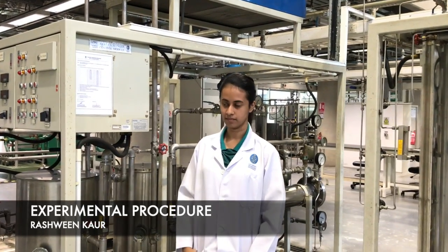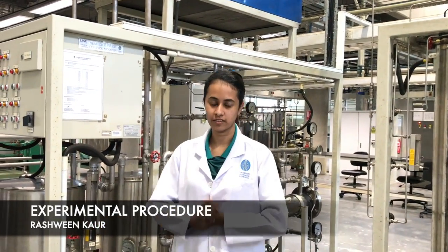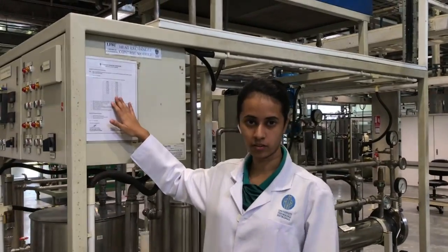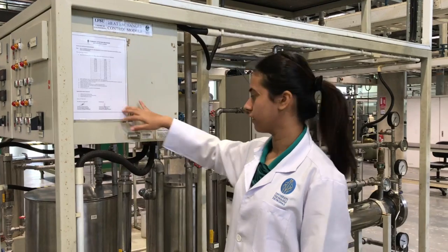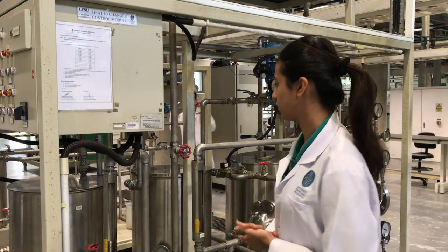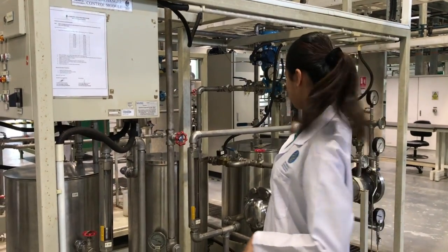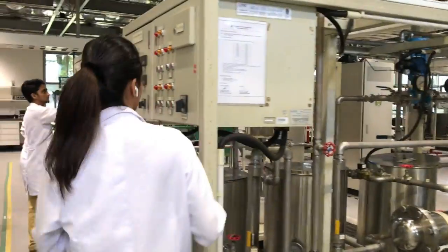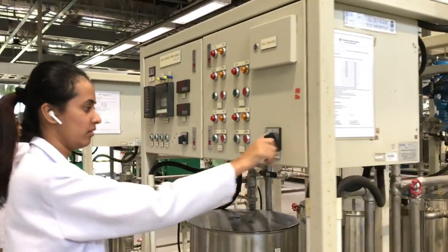Hi, my name is Rashmi, and today I'm going to talk about the procedure of this experiment. So first of all, for the general setup procedure, we will have to ensure that all the valves are set according to what's written over here, and which valves are supposed to be open and closed. After that, we need to fill in the cold tank and the hot tank. And then after that, we can switch on the main power,